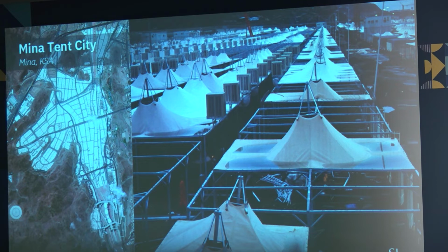There are no surfaces that can be exposed to strong winds or rains or any of that. Therefore, we keep the steel structure very light. In addition, for this special project, there was the requirement to find a material which is non-combustible, as these tents are standing very close to each other, and pilgrims like to cook their food, so they have open fires, which was a big challenge at the time.